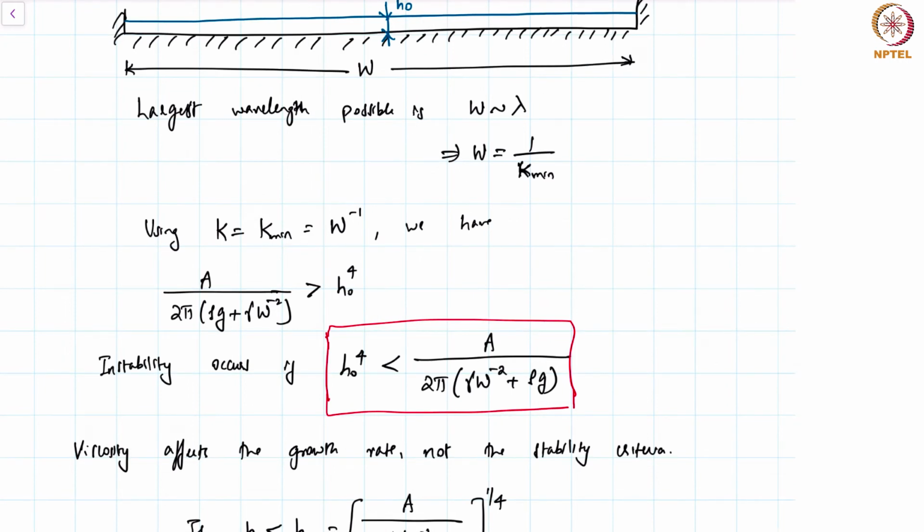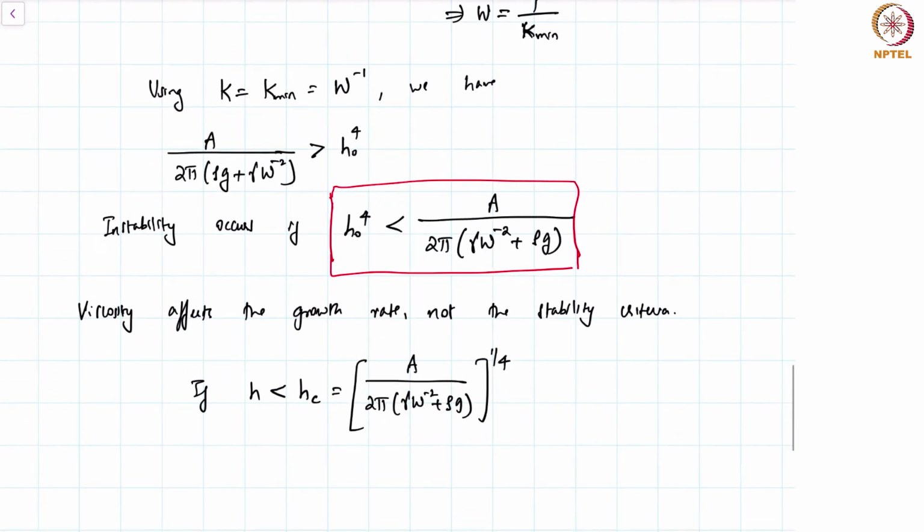Now, if the thin film is thicker than a certain value, meaning greater than this critical thickness, Hc, then you would expect that the van der Waals forces are not very dominant. But there are many other physical processes at work in a real laboratory experiment. For example, the thin film could constantly keep evaporating, and there will be a point where the thin film thickness becomes comparable to this Hc. And then once this happens, van der Waals forces will eventually drive the thin film to rupture.